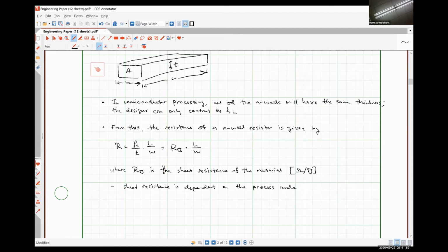So poly 2 to poly 1, metal 3 to metal 2, metal 2 to metal 1, metal 1 to the substrate, all kinds of things like that, because those vary literally every manufacturing run. So we can try to best guess what it's going to be based on published data, but we have to design to accept small variations in tolerance, because there are small variations in tolerance in the way that wafers are created using the Czochralski method.